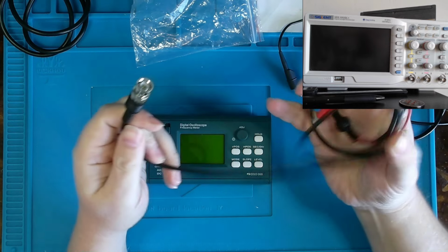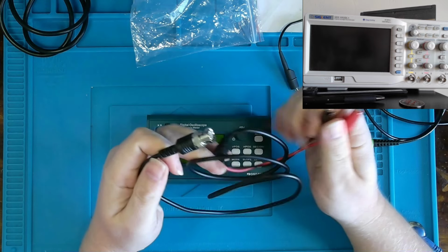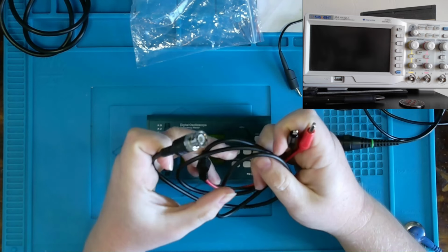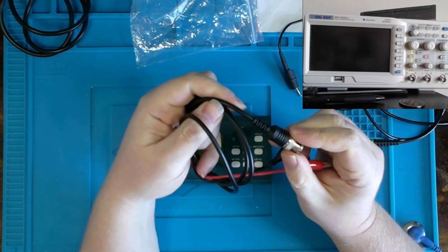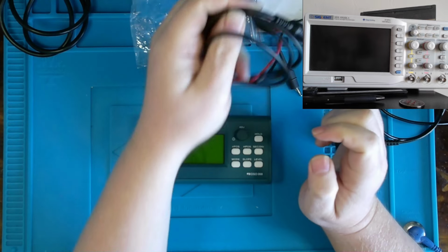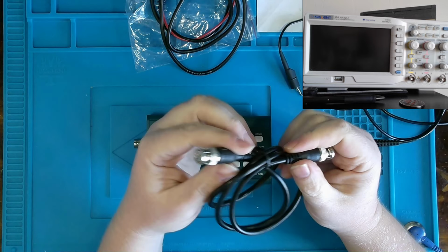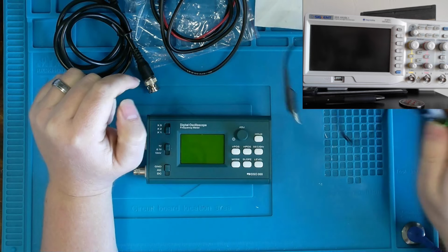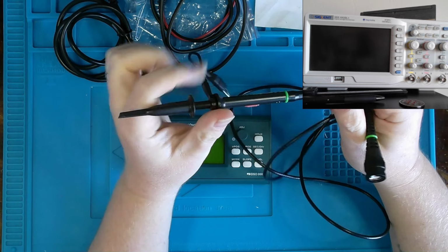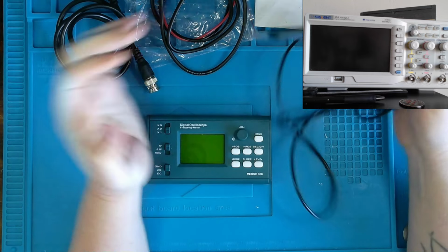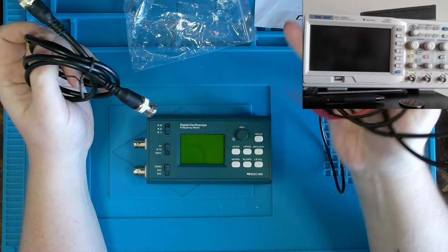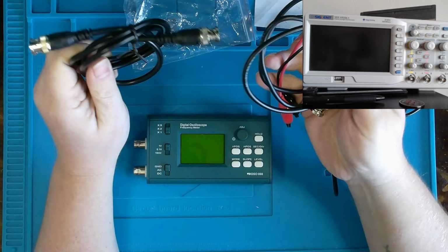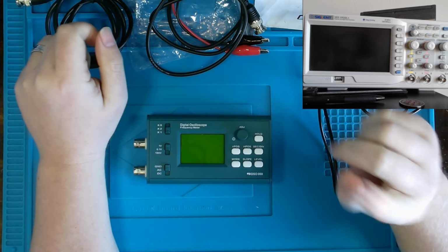You can also use a device such as this, although it's very uncommon. It's a typical BNC to alligator clip. Most often these are a 50 ohm cable, so you need to keep that in mind, as well as a traditional BNC to BNC 50 ohm cable. The impedance of which is actually very important because these scopes are usually 1 megohm impedance, whereas these types of, I wouldn't call them probes, but connectors, cables, are 50 ohms. So something to keep in mind.